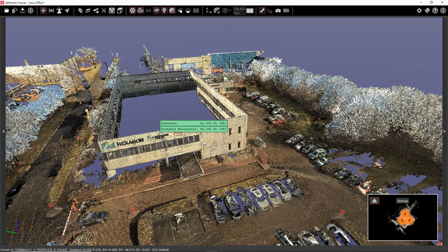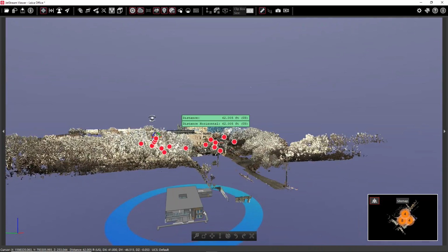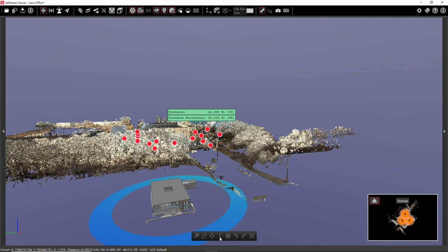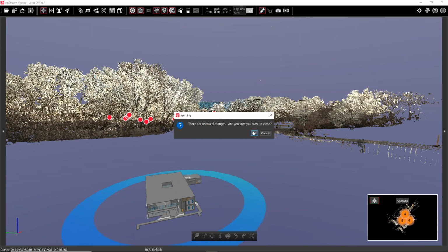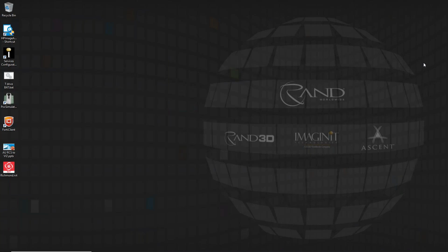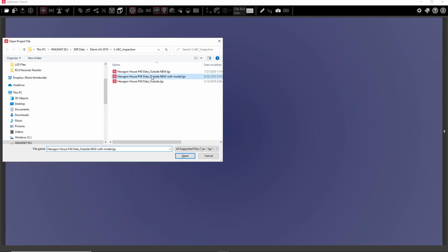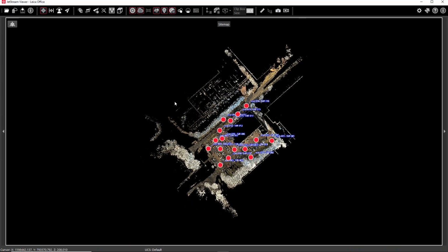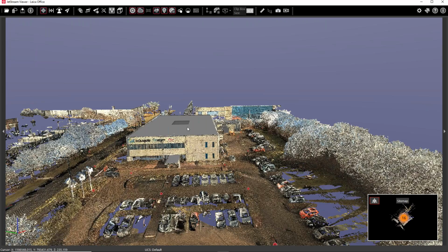Okay, I'm going to use the model coordinates, and you can see, oh, geez, what happened? My model doesn't line up perfectly. Well, there are tools in here that will allow me to move this. And of course, it's not going to work when I'm ready to demo it. So bear with me one second. It often happens when it just needs a good restart. There we go. So the model can be moved around in the point cloud to line up with the point cloud.